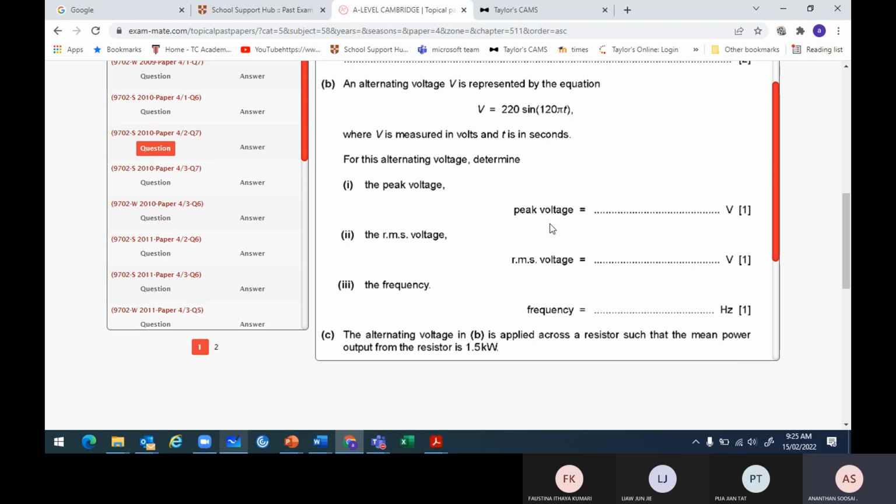Because the power formulas I squared R and V I originated from DC. So AC is another planet. Now we found that the value equivalent to this is the RMS value, so you have to use RMS. Here you have to use V squared over R, and V must be the RMS value. So what's the RMS value here? 220 divided by √2, and you get the RMS value.